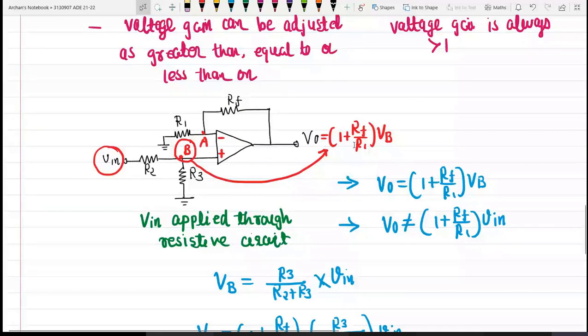Okay, so this fact will help us to analyze some complex operational amplifier circuit in which a non-inverting amplifier is a subpart. Remember that a non-inverting amplifier always amplifies the voltage at its non-inverting terminal. This is the most important, remember, right?